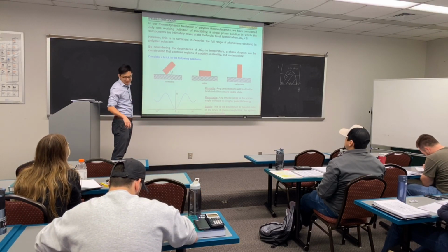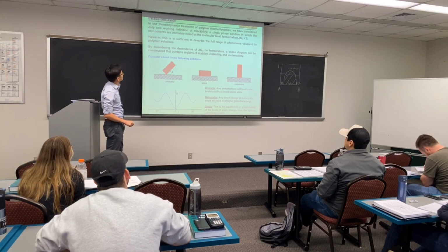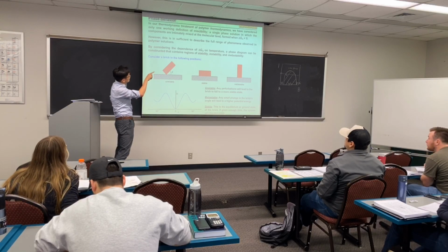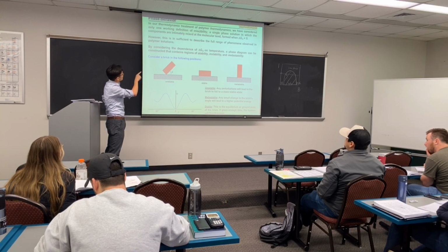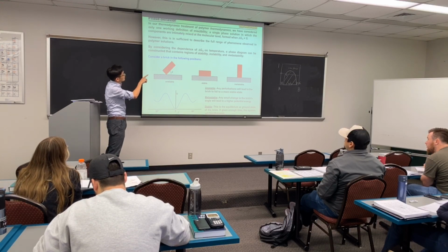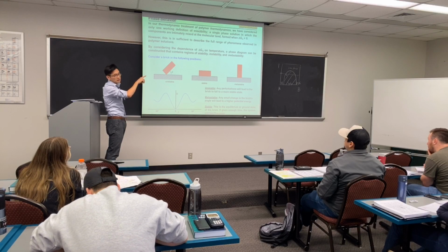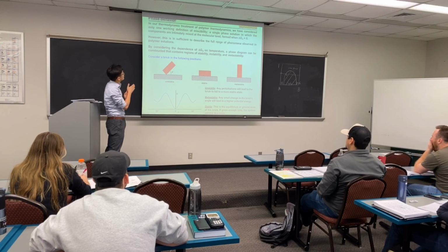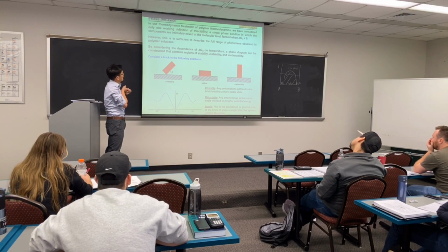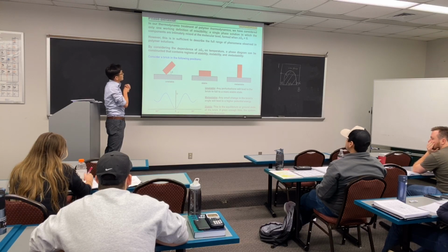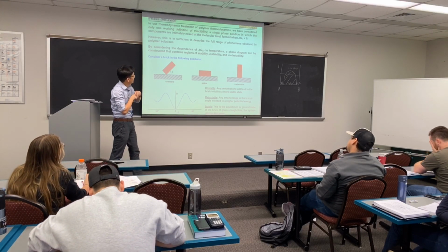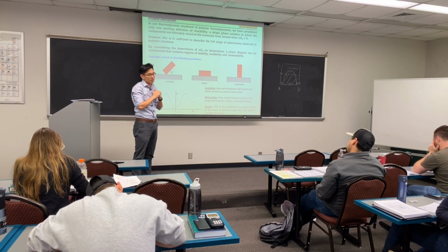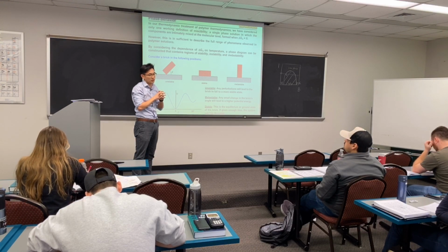In thermodynamics, there's only one working definition of miscibility: a single phase in solution in which the components are intimately mixed at the molecular level. It only forms when delta G is smaller than 0, which means they will be spontaneously mixed. So we just need to understand the dependence of delta G on temperature, and we can construct a phase diagram. Previously we didn't talk too much about temperature, and in this class, temperature is becoming more important.